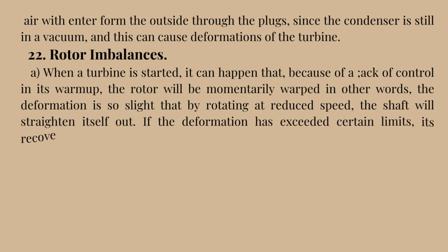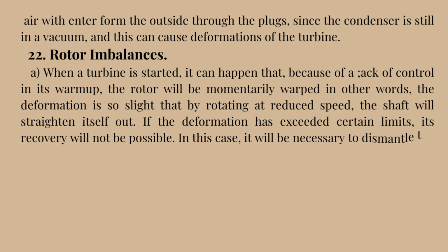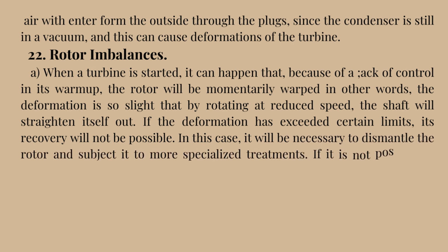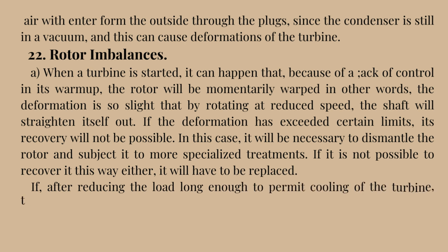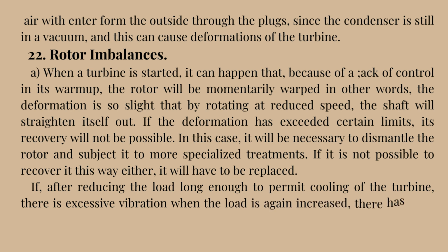If the deformation has exceeded certain limits, its recovery will not be possible. In this case, it will be necessary to dismantle the rotor and subject it to more specialized treatments. If it is not possible to recover it this way either, it will have to be replaced. If, after reducing the load long enough to permit cooling of the turbine, there is excessive vibration when the load